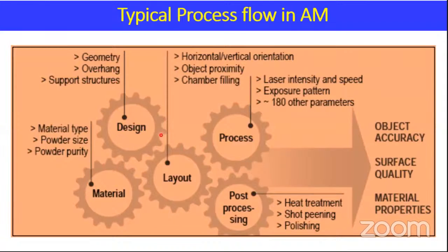And eventually these aspects will be covered or thought about in the design phase, a very involved process, along with the layout when we manufacture this part: in what kind of configuration we are going to manufacture it, whether we keep the part in a horizontal direction, vertical direction, or inclined orientation, and what kind of job proximity, whether we can print only one part at a time or multiple parts at a time, and what kind of atmosphere is maintained inside the chamber within which the part would be manufactured, right?